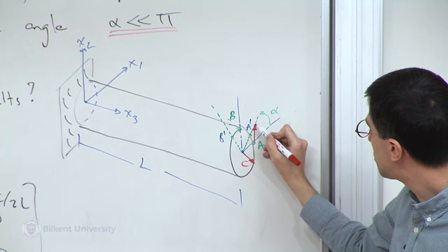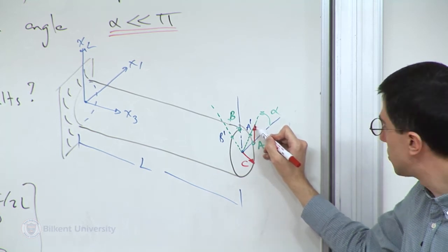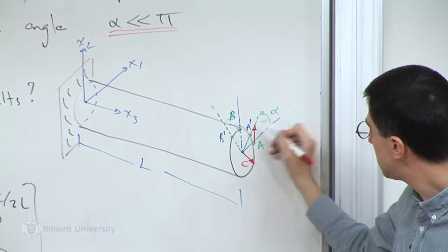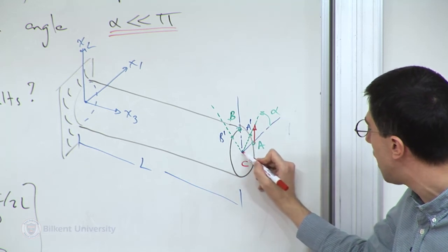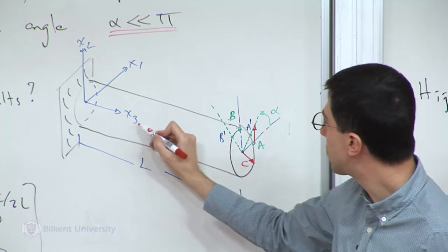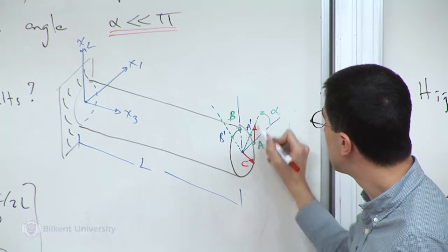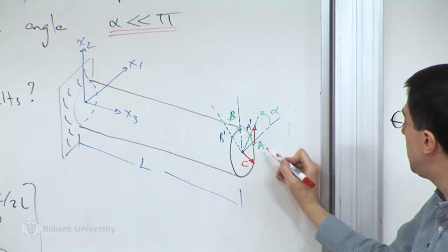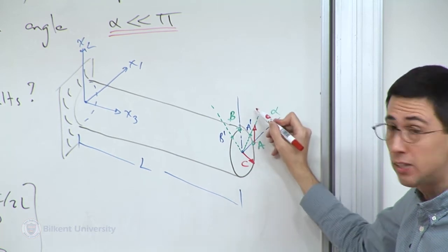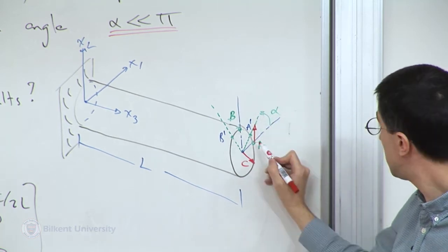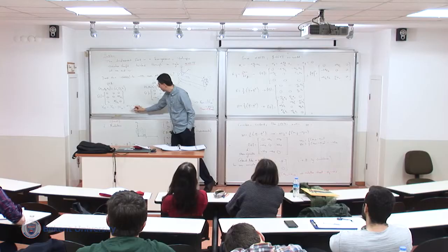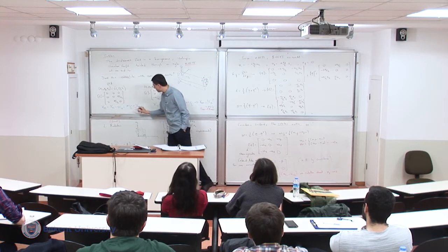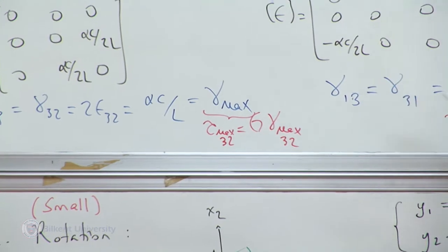So this is a stress component. And remember, we always used to say, well, stress component takes 2 indices. The first index is I'm on the plane with normal 3, in the direction upwards 2. So 3,2. And if it is positive, it points upwards. So it is pointing upwards, it's supposed to be positive. And so shear stress, and therefore tau 3,2 is positive.